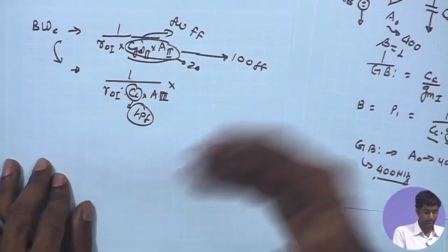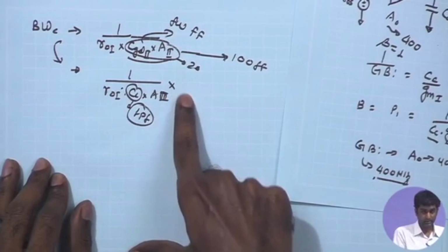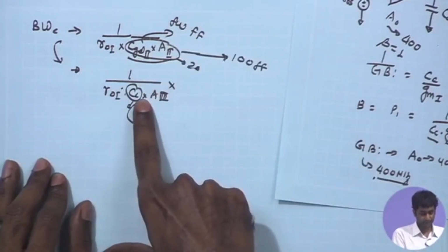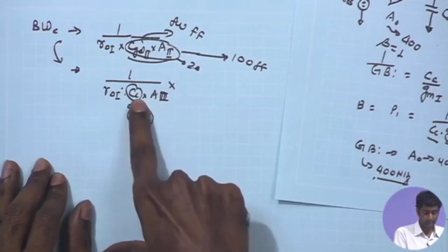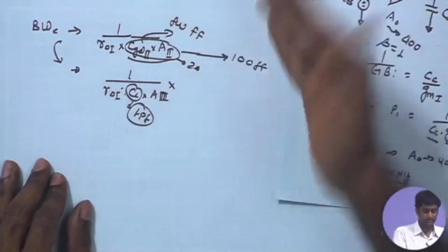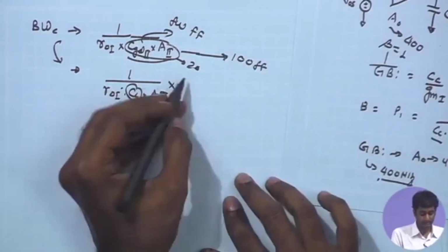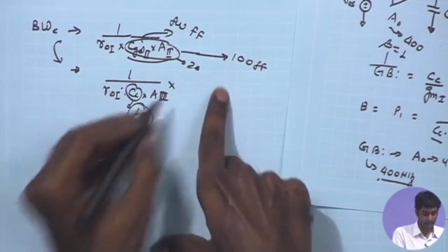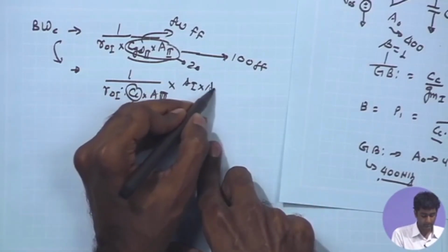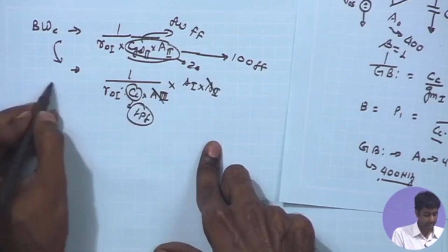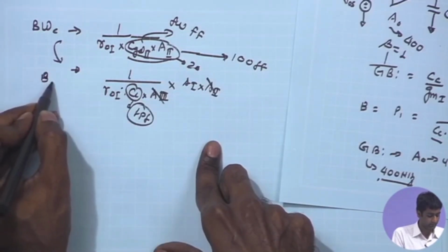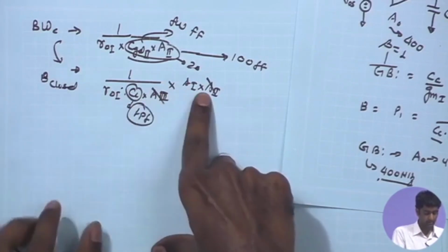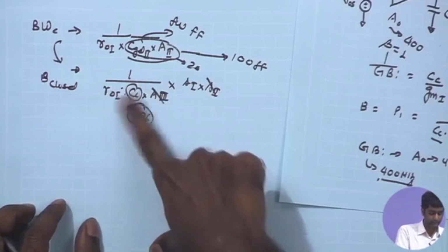But apart from that, we also have the overall gain, right. So, this is the open loop bandwidth given by the first pole and the Miller multiplied CC, the compensation capacitor. This is multiplied by the 1 plus A beta factor. Once again, A beta is approximately equal to A, which is A1 times A2, where A2 gets cancelled, and therefore the closed loop bandwidth is going to be A1 times this number.